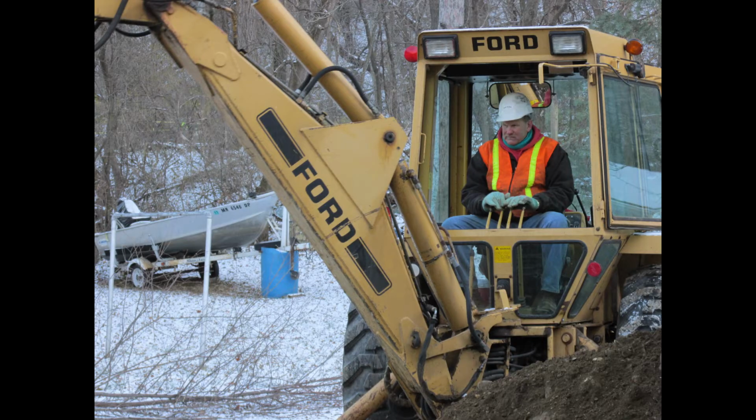Excavations. At a job site that may have excavation edges that will not be readily seen, i.e. concealed from view by plants, etc., and when the excavation is 6 feet or more, we protect these excavations by, number 1, guardrails. In addition, walls, pits, shafts, and similar excavations 6 feet or more will be guarded to prevent employees from falling into them by, number 1, guardrails and/or fences.